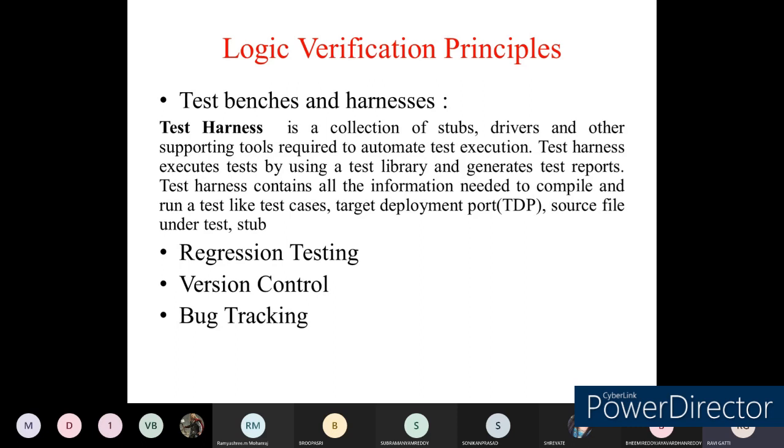Okay, so in the behavioral simulation I go for the creation of test benches. In these test benches, I will create all the combinations of the input sections, starting with the 3-bit 0 0 0, that is the first stage, and the final input stage we can get is 1 1 1. For all these cases I need to make sure that I get a correct realization of the sum expression and carry expression. So we are going to create test benches.